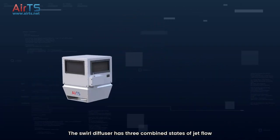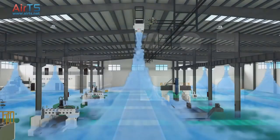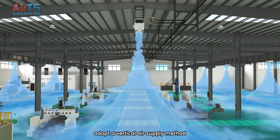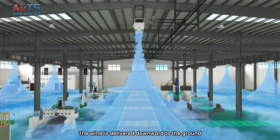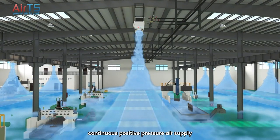The swirl diffuser has three combined states of jet flow: swirling flow, diffuse flow, and intermediate transitional flow. In the normal cooling mode, adopt the vertical air supply method. The wind is delivered downward to the ground, and the cold air spreads along the ground to all sides under continuous positive pressure air supply.